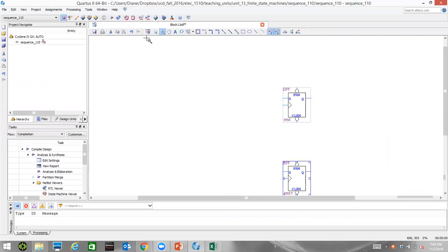Okay, these D flip-flops in this library, this triangle is our clock input. Here's our input to D. Here's our output Q. These also have a preset. So PRN is a preset, meaning if you wire a preset signal to that, whenever you assert the preset signal, your output of Q will be a 1. CLRN clears it, it's a reset. So if you were going to assert the reset signal, your output would be a 0. We'll actually just not wire that at this point.